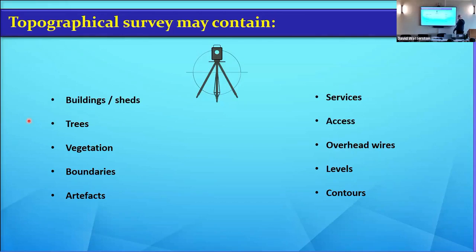Because you might be blocking up, which will then introduce damp errors, or you might introduce the lack of light, right of light to the basement. Even though it's your client, he still wants that light downstairs. So overhead wires, very important. If you're bringing in established mature trees, you don't want it snagging on anything overhead that wasn't picked up in the survey. And that can be cables, BT, pipework, whatever, even over large overhanging trees. So it's anything that can get in the way of you bringing stuff to site that you would need on the survey as a record, so you know it's there. Because generally people, surveyors and everybody, are walking about looking at ground level, we're never looking up to see what's going on up above them.